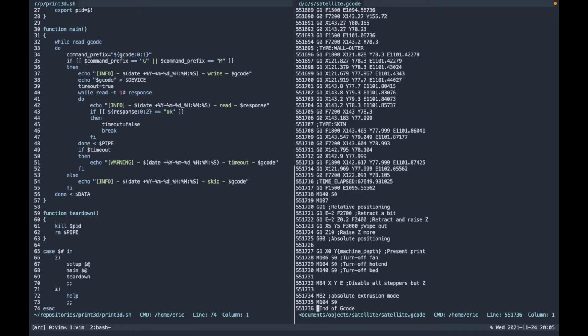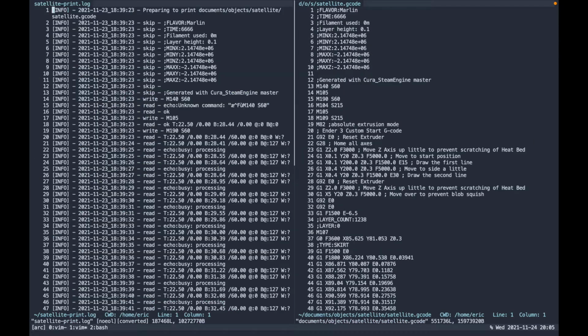Now, what we want to do is find exactly where the 3D print stopped, and once we have where it stopped, we should be able to find in the actual print file where we need to pick up again. We'll add a few commands to that so that we can move it up on the x-axis, get the hot end to the appropriate temperature, we'll move back down, and then we'll resume. So let's talk about how we're going to do that. I'm going to move to this next window here.